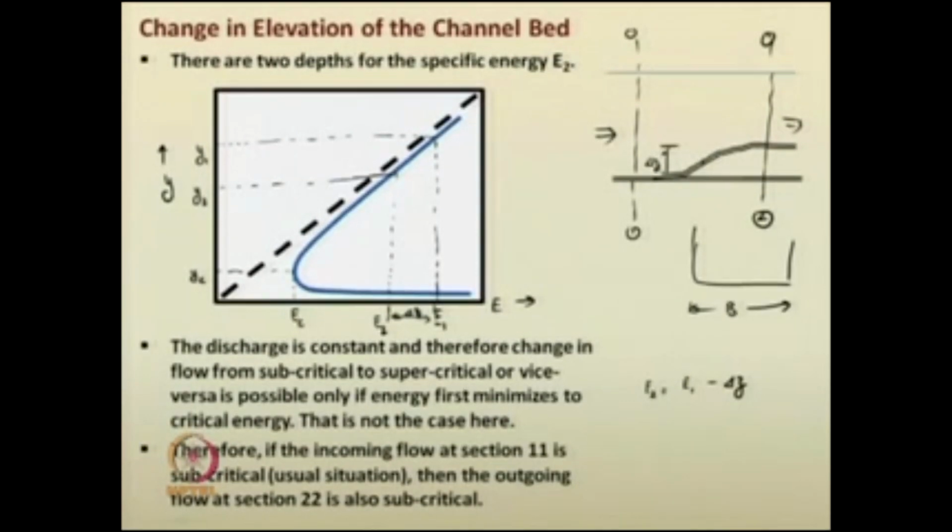So, from here you will just see what is Y2. This Y2 can be above this water surface, or it can be below, or it can be same, that we do not know. Based on the exact numerical value, you have to identify it. So, you will be selecting the corresponding subcritical depth Y2.